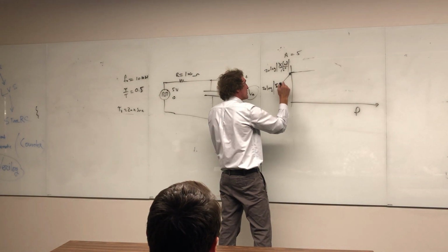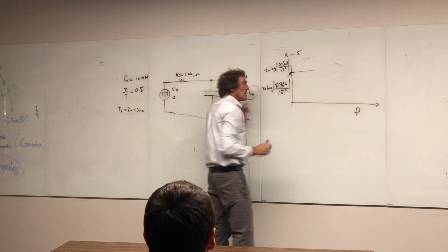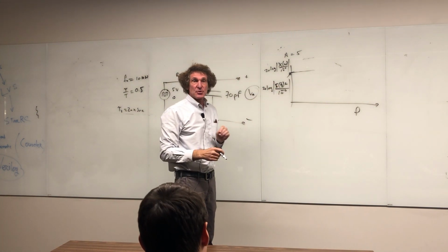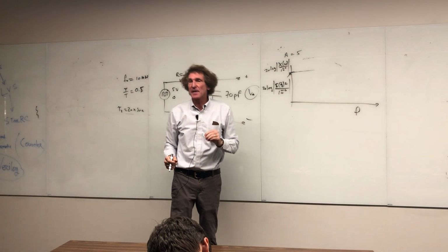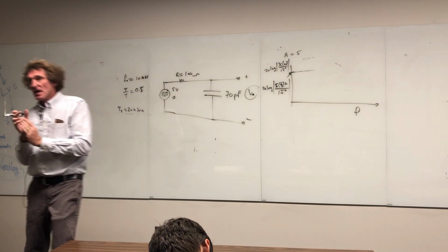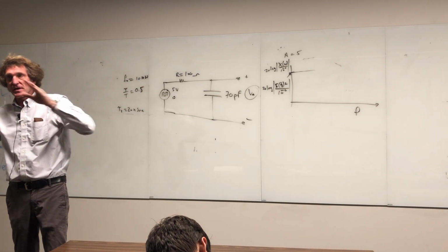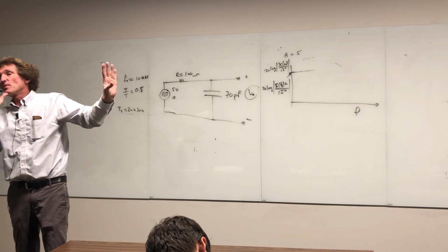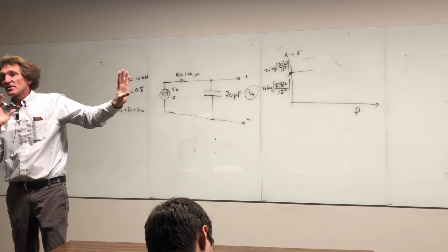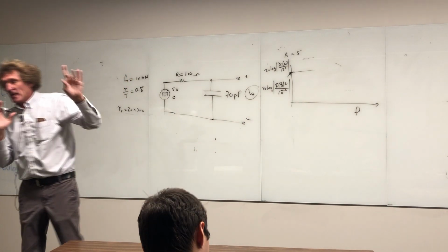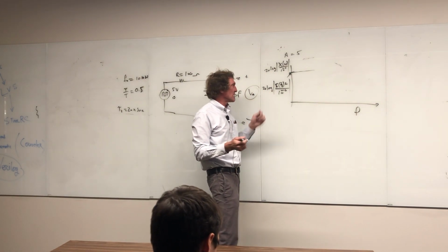right? Duty cycle is 1/2, but then there's the factor of 2 that comes in, divided by 10 to the minus 6. Now, the 1/2 has to do with the duty cycle, right? It's tau over T. The factor of 2 comes in because that really is the coefficient of the cosine series. And remember, we took the Cn value from the series that was doubly infinite, that went from minus infinity to positive infinity. Then we made it a series that just goes from really 1 to infinity plus C0, right? And that value has the factor of 2 in it. Do you all see what I'm talking about? So that comes in there. So I have 5 times 1/2 times 2, or really 5, right? Over 10 to the minus 6 times 20.